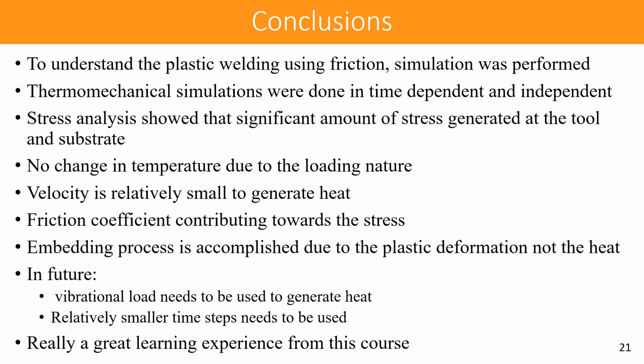And then another thing I investigated is that changing the frictional coefficient is not really contributing in all cases, but it is contributing towards the stress in transient analysis. Although it's very small, it's not a really big difference between 0.5 and 0.2. And then the embedding process is accomplished due to the plastic deformation, not the heat. So that means I was trying to verify that it's not about the melting, but about the plastic deformation of the substrate material right under the tip.